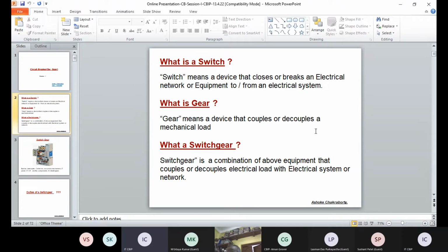And if we want to break it, whether the load is inductive or resistive, breaking the load current becomes quite difficult, because the piano switch does not have any mechanism to handle the arc. Whenever there is a breaking in the switchgear, some arc will be involved. Do you know why the arc will be involved?